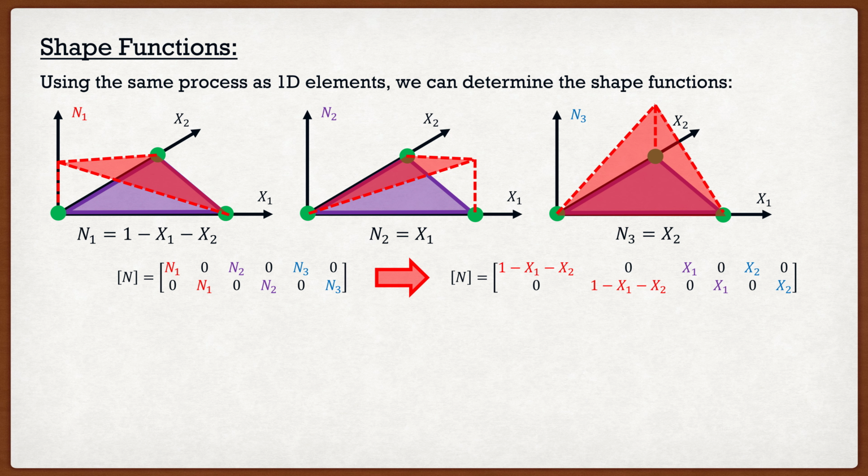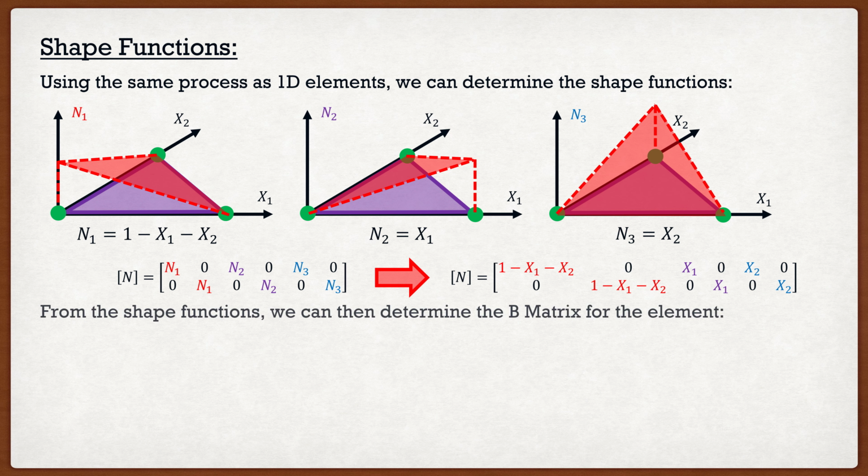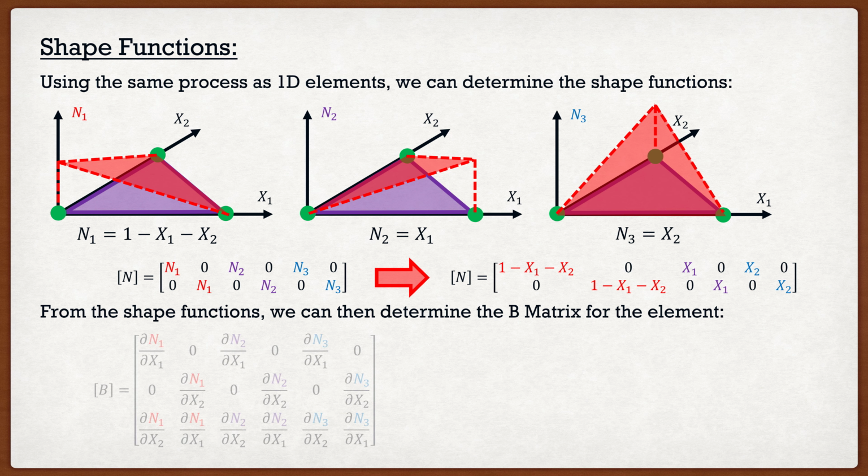And we said that this is great because once we know what those shape functions are, we can actually use it to determine something called that B matrix, which again related the nodal displacements to the strains of our elements. And we said that our B matrix actually has the following format. Now, yes, this is very gross. No one wants to deal with this, but it's nice because one of the things that we said was that this B matrix is very repetitive.